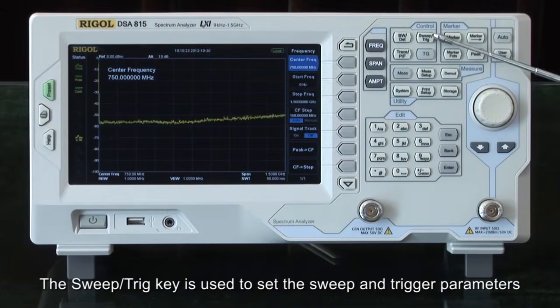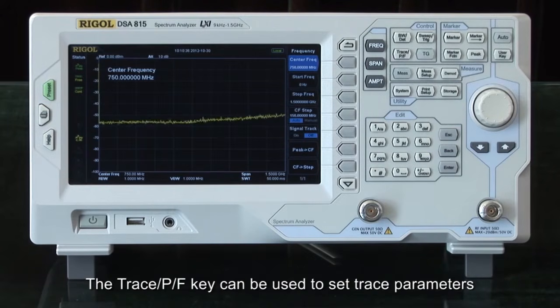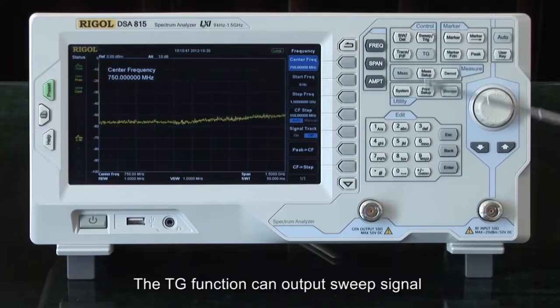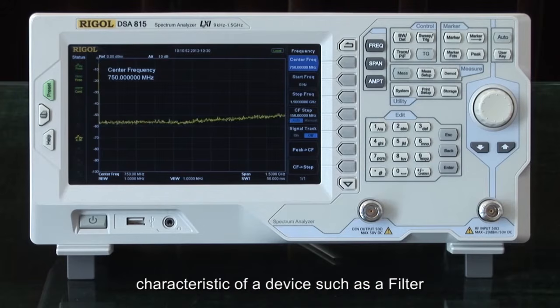The sweep trig key is used to set the sweep and trigger parameters. The trace pass-fail key can be used to set trace parameters and configure the pass-fail testing. The TG function can output the sweep signal, which can be used to analyze frequency response characteristics of devices such as filters and amplifiers.